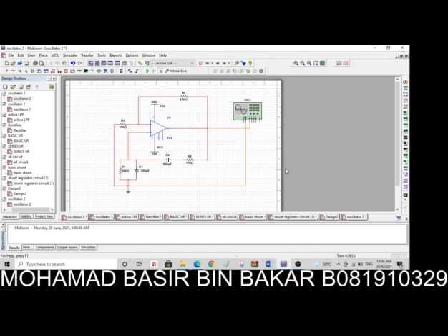As you know, the Wien bridge oscillator uses a feedback circuit: a series RC circuit connected with a parallel RC of the same component values. So it produces a phase delay or phase advance depending on the frequency. In particular, one arm has a resistor and capacitor connected in series, as you can see R2 and C2, while the other has them in parallel, C1 and R1. These two arms behave identically to a high pass filter or low pass filter. As you can see, C2 and R2 is a high pass filter, and C1 and R1 is a low pass filter.